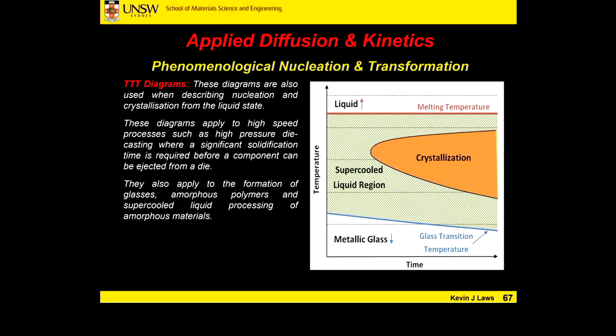It's the most stable glass there is, just because of its chemistry and its molecular structure to be more accurate. Silicate glass is very, very stable and has this rotational degree of symmetry about its molecular structure, or its preferred covalent structure, that lets the energy between the crystal and the supercooled liquid be almost equal to one another. And it literally takes centuries before silicate would even think about crystallizing at room temperature.